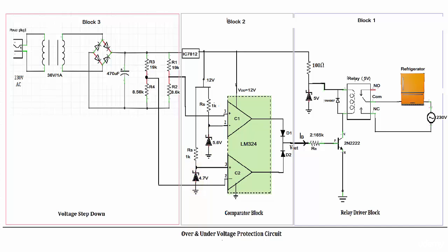Now I divided the voltages here to some intermediate value in between 4.7 volt and 5.6 volt, which are my reference voltages. Whenever the supply voltage goes low, the voltage at the filter's output will also go low and it may decrease to a value less than 4.7 volt.